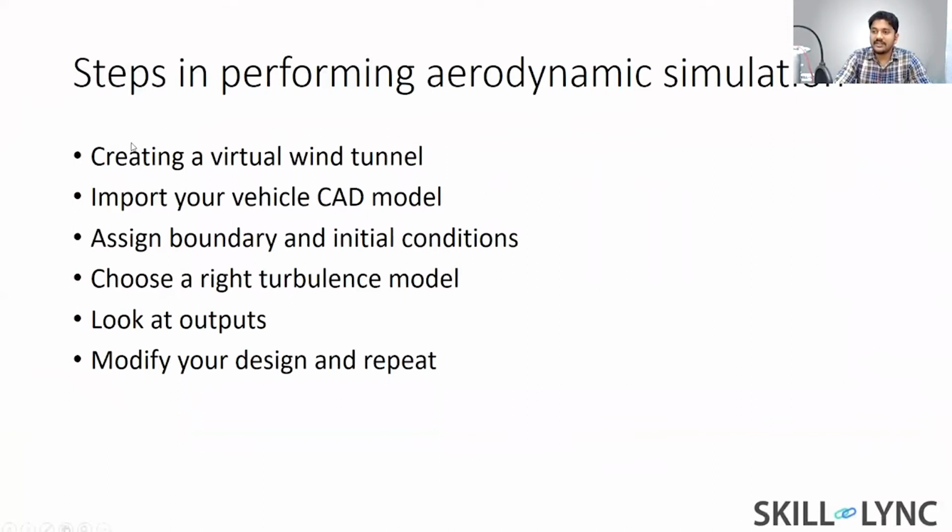All right, so basically these are the steps that you need to follow. Once you follow these steps, you are going to get some results, right? You need to always get a baseline result, meaning a set of results that you will always come back to and refer to. Any design changes should be done only after you have already simulated the baseline design. Change it and then compare it.